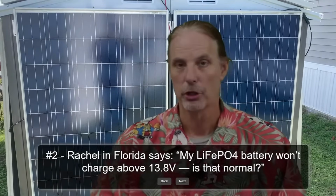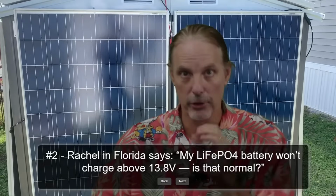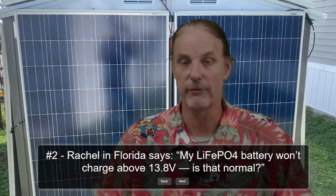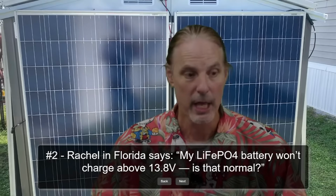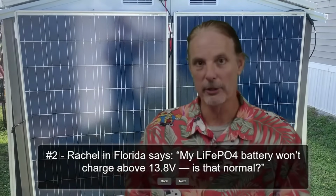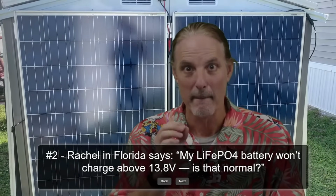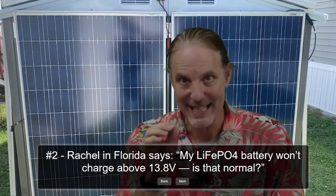If it won't charge above 13.8 and you have the correct configuration, you do have a proper charger, and you do have the voltage set to, let's say, 14.2 or 14.4 for the standard profile charging, then what it can be, and I'm going to need to run back to the board to explain this one, is yet again another case of the BMS state of charge being inaccurate.